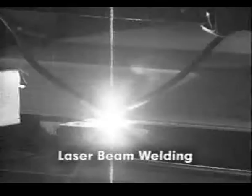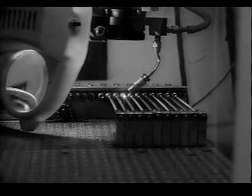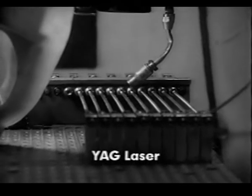In laser beam welding, the heat for coalescence is generated by a focused beam from a gas or solid-state laser. The most commonly used gas laser is the carbon dioxide or CO2 laser, which is actually a mixture of carbon dioxide, nitrogen, and helium gases. The most commonly used solid-state laser is the neodymium-doped yttrium aluminum garnet, or YAG laser.